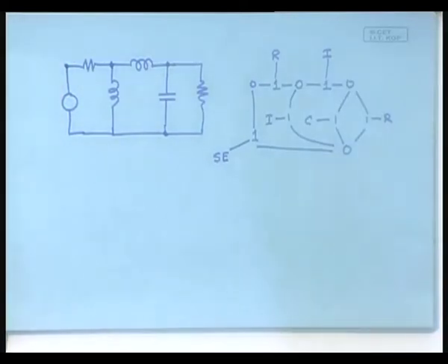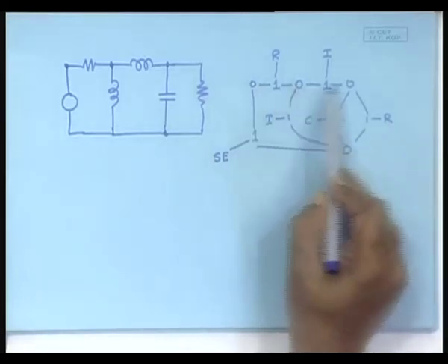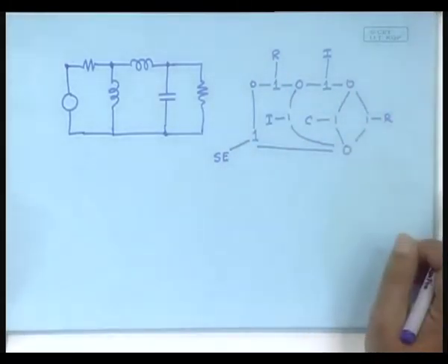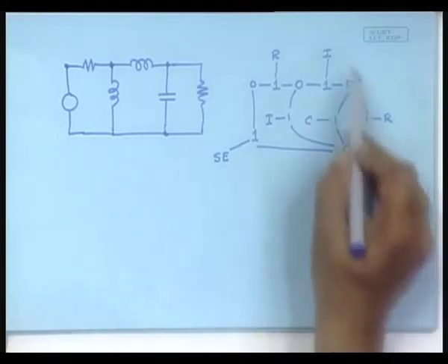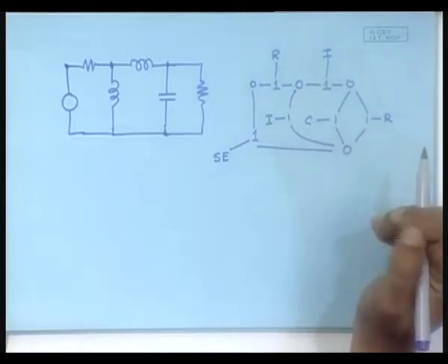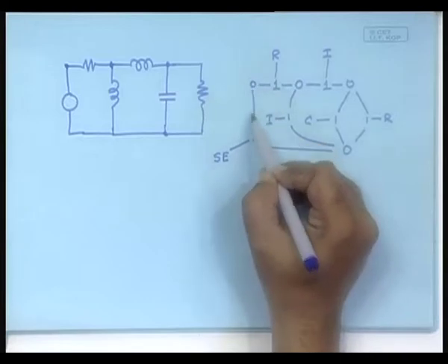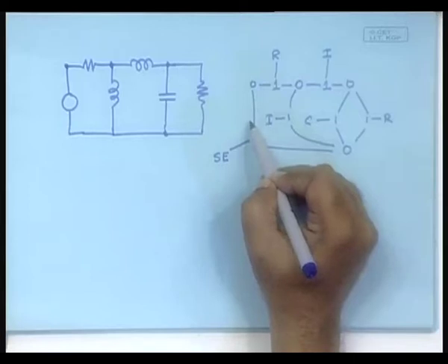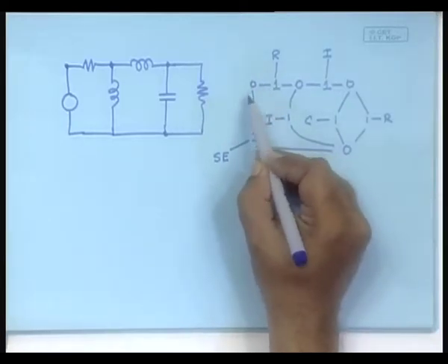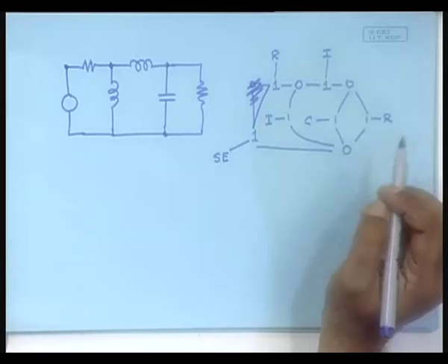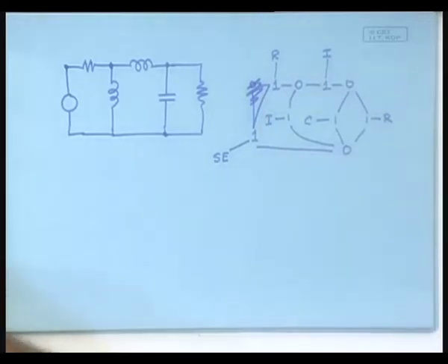Okay. We have blindly done it. We have just said that these 4 points represent different voltages, and in between, whatever is connected is by 1 junctions. Done. But now we have landed up with a bond graph that contains more bonds than you really require. For example, this is a 0 junction which is connected to only 2 things. Therefore, the effort that comes here must go here, and whatever flow comes here must go here. The powers are equal, and the effort and flow are also equal. Therefore, this 0 junction serves no purpose. You can short it. That is one way of shortening the bond graph.